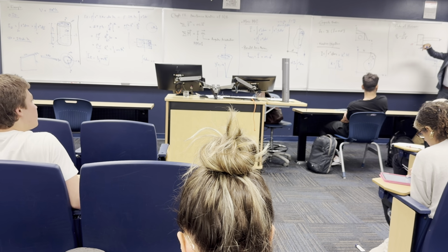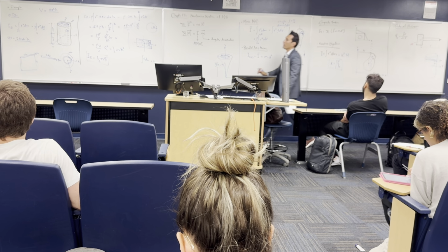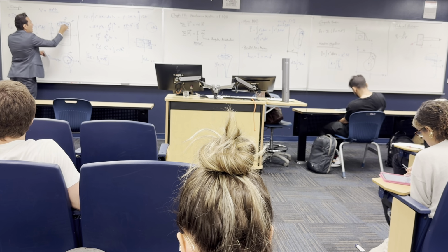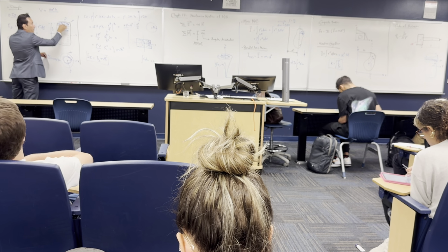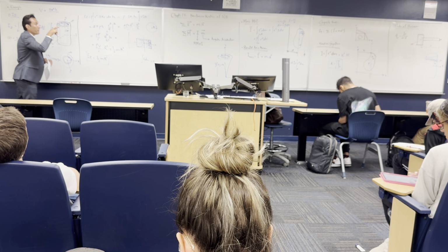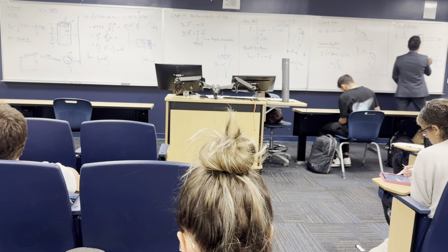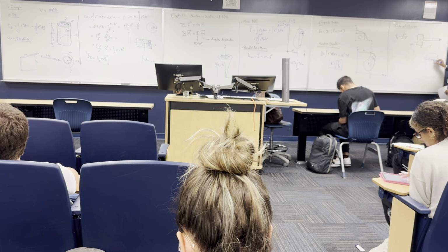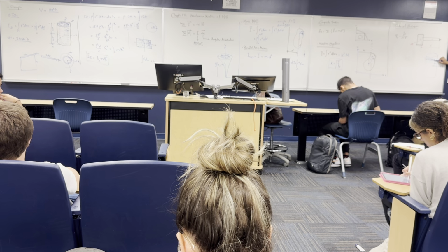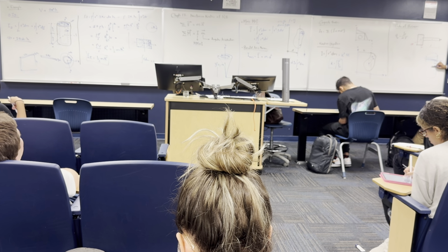We take a strip around the CG, around the axis that we are taking the moment of inertia. So, like here, this circle is about my CG here. So I'm taking still the moment of inertia about the CG, but this one, the x is down. Like the CG of this mass is here. So what I want to find out is the moment of inertia about this axis, and then transfer this to here. So I need to do the parallel axis theorem.